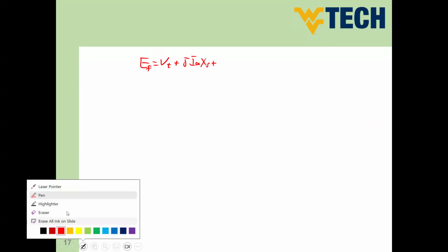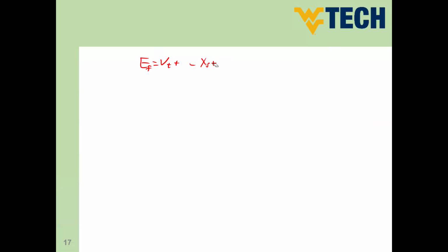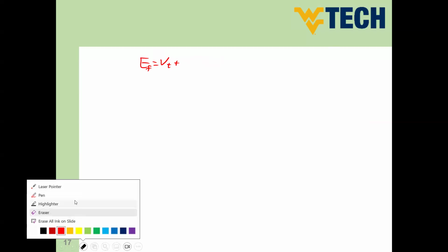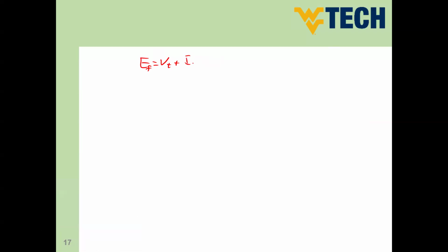Let's see now how to draw the phasor diagram. So this is our relation again: EF equals VT plus IA times RA plus JIA times XS. Sorry, let me write down the resistance first. So this is our mathematical model. Let's draw the phasor diagram.